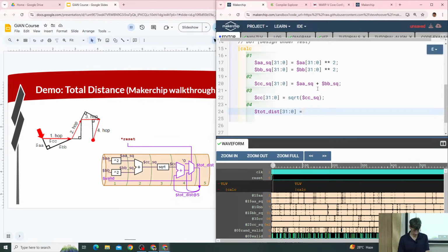This mux has a reset condition. I'm just directly hooking up the SystemVerilog reset signal. It's a little bit cleaner to create a pipelined reset. That makes the code properly timing abstract, right? When I refer to a SystemVerilog signal like this, if I change this from @4 to @5 for some reason, I'm not guaranteed to preserve the overall function of the design because I'm not using pipe signals. Okay, so if I change this from 4 to 5, I'd be hooking up to the same reset signal with a different timing, and that can affect the function.